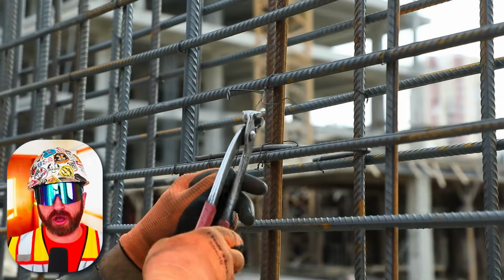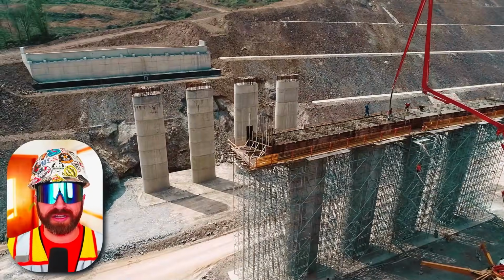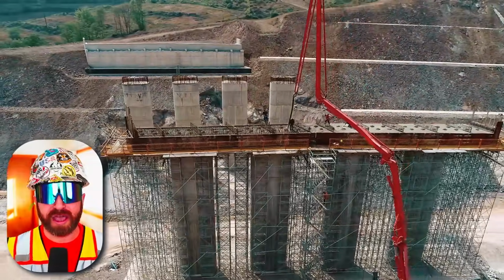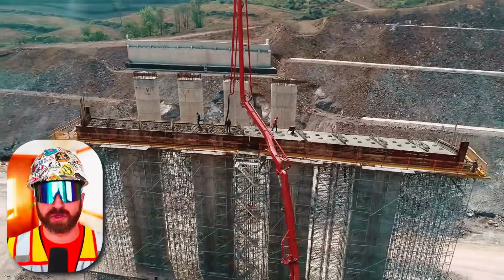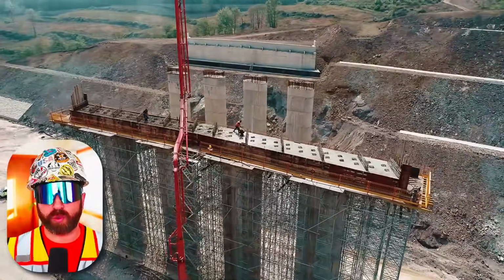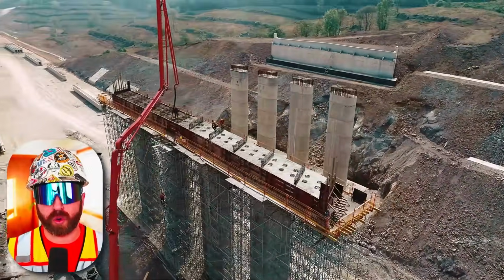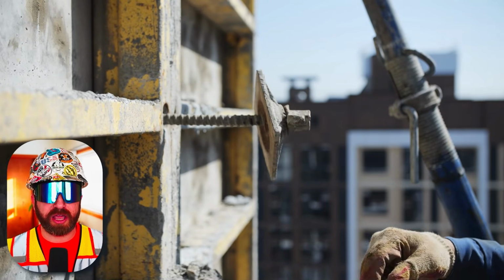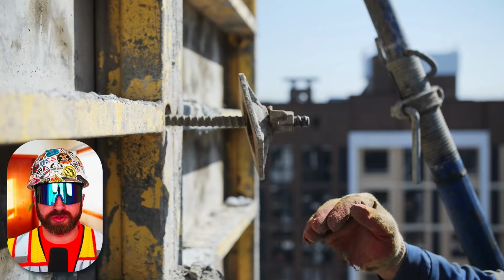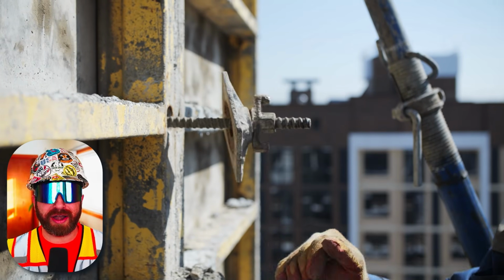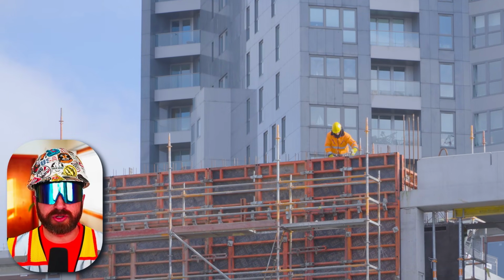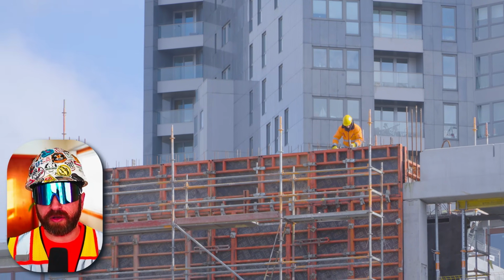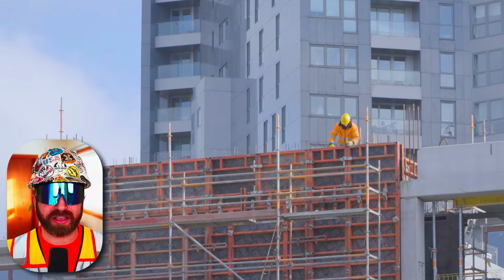So the rebar is installed, but before you pour concrete, you need to place any sleeves for piping that passes through any foundation walls, any anchor bolts or embed plates that support the steel, as well as your formwork that shapes the concrete as it's poured, typically formed by a carpenter. Now, formwork will come in a variety of types depending on the complexity of the project or the scope, which I'll make a separate video on in the future. Sometimes formwork is so complex that it requires its own set of shop drawings, but just know that formwork itself is not detailed in the construction documents.